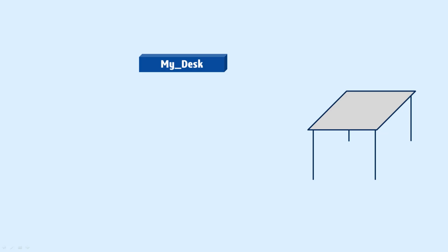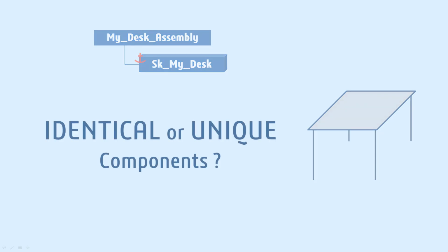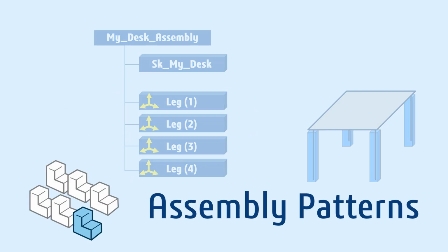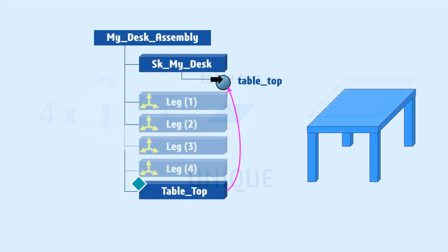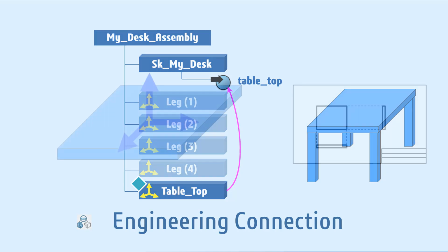Conclusion. Start the design inside one single part. Once ready for assembly detailing, insert it below product, lock its position in space and use it as a skeleton. Identify as many identical items as possible and use assembly patterns to locate them. Design them in local axis system. For unique items, you can use external references, and you can also design them in a local axis system to simplify drawing generation.